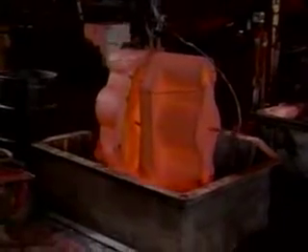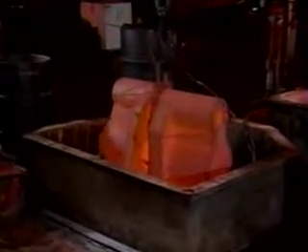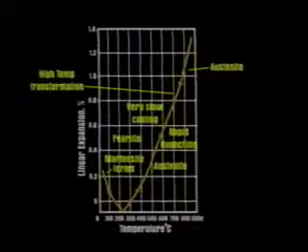One of the most important and least understood operations in heat treating is quenching. Quenching refers to taking metal that has been heated to the hardening temperature, then cooling it to a lower temperature in such a way as to maximize the formation of the desired microstructure, usually martensite, which will produce the necessary hardness, strength, and toughness.